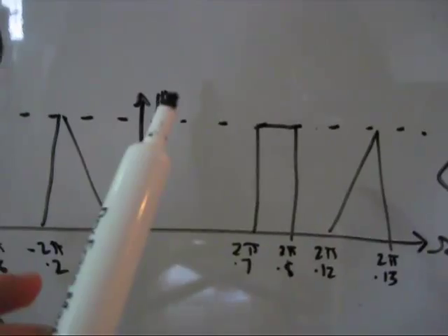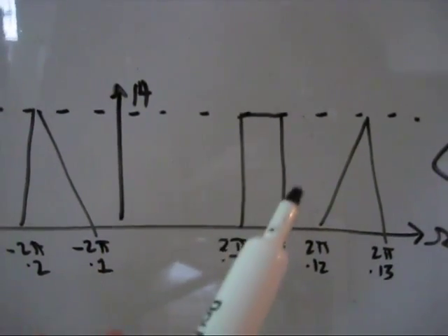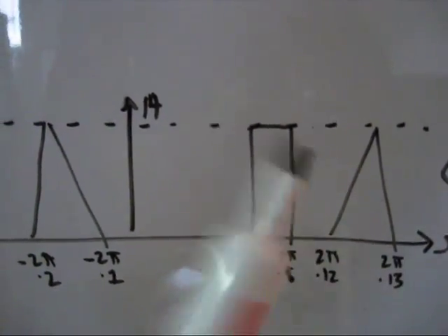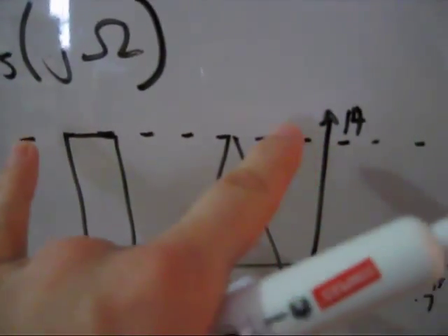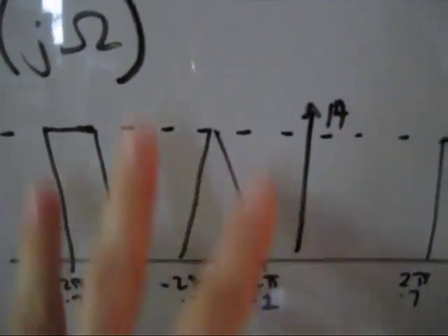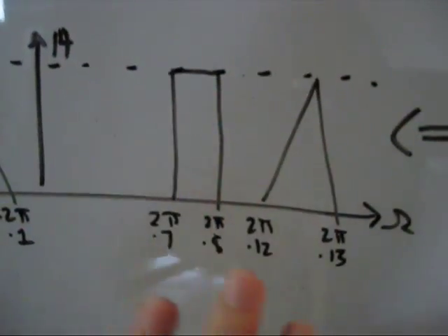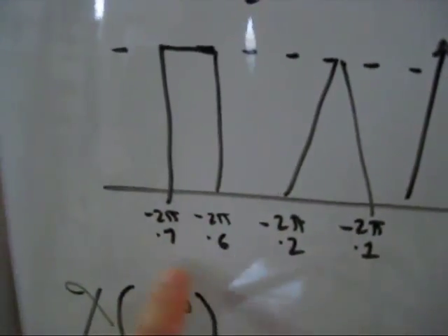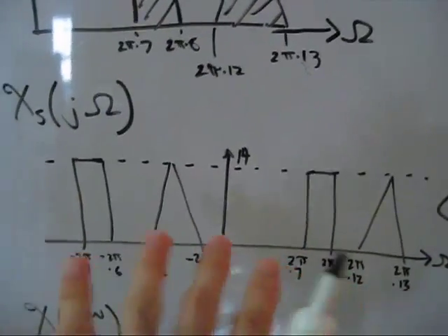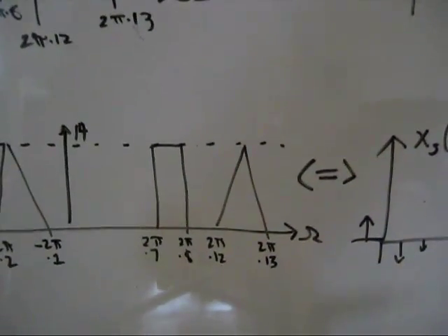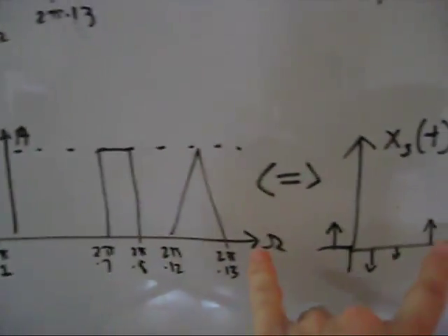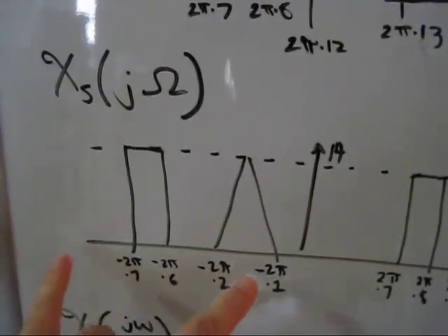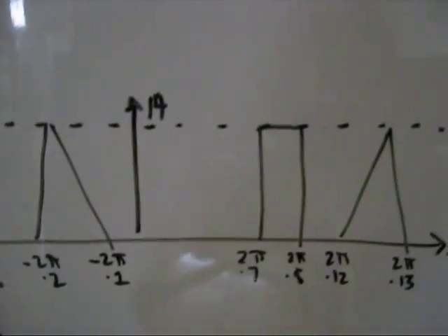So when you sample a signal, what you get in the spectrum of your sampled signal is replicas, okay? So replicas. I just dropped the eraser. This right here is a replica, see, because this was our original part, right? These parts here, that was our original part, and this is a replica. And if you were to take this graph and expand it out in both directions, you would see that it would continue to repeat, again and again and again, in this direction too, off away until infinity.